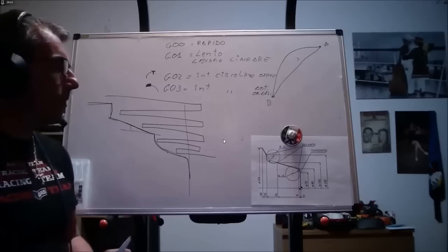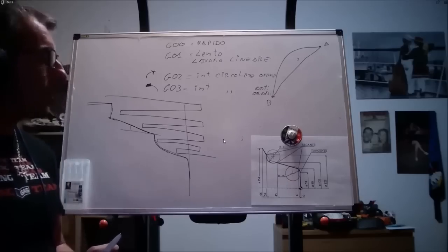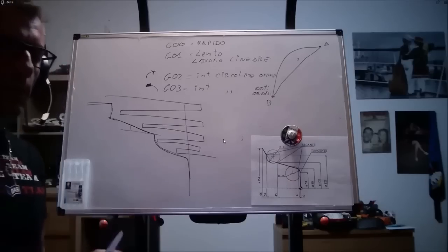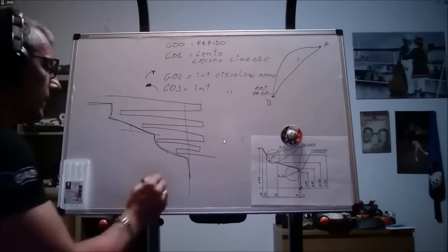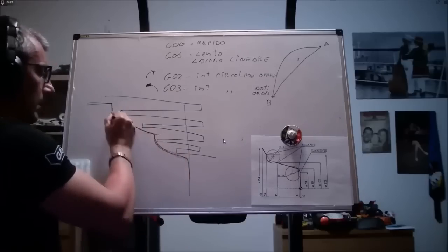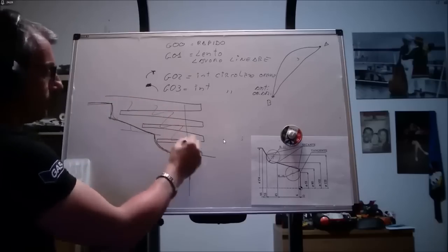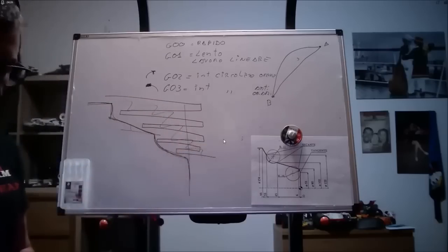Fortunately, our machines also have direct programming, so we can program angles, fillets, and chamfers very easily. And we also have macros that, once the profile is used, do all this work for us.